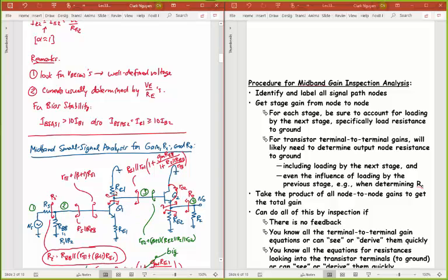When we wanted to get all the resistance at this node, we looked at that RC, but we also looked even at the resistance looking down this way back into Q1, and we looked at the resistance going in that direction. These other resistors turned out to be very small, but that's not always the case, right? If it wasn't the case, then I couldn't just write RC1. I'd have to write down RC1 in parallel with these other resistors.